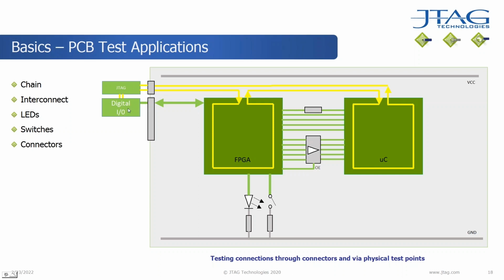You can fool the system into thinking that the connector here is a boundary scan element, and thus you can test that continuity as well. In most cases we actually use a separate test access port, but you can serially link the devices on the board with the devices off the board if you choose.